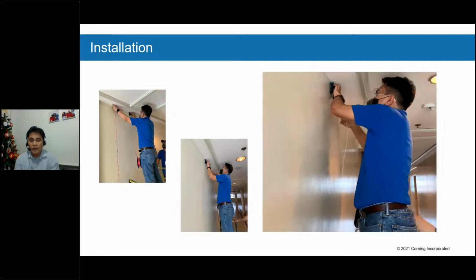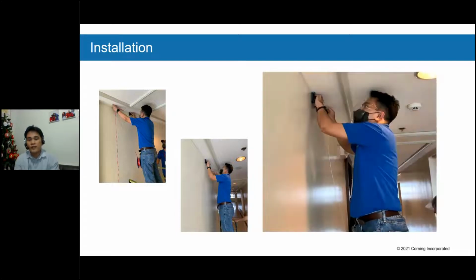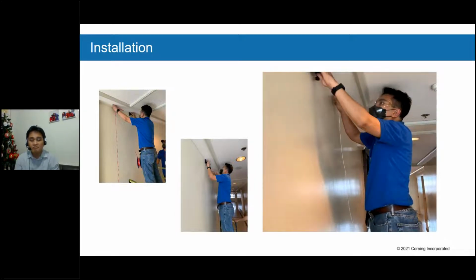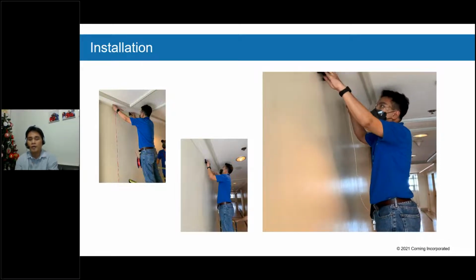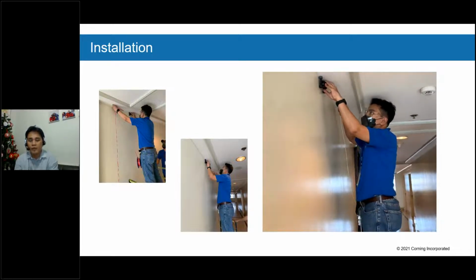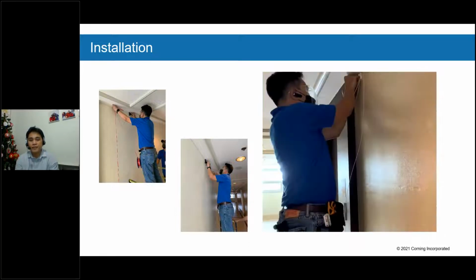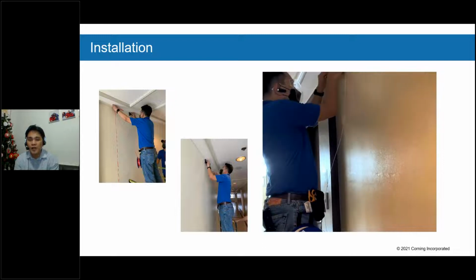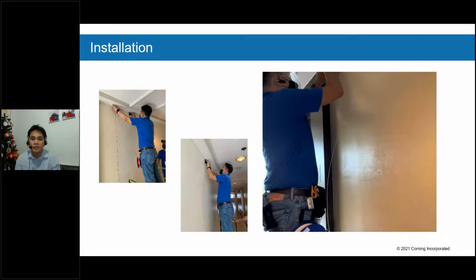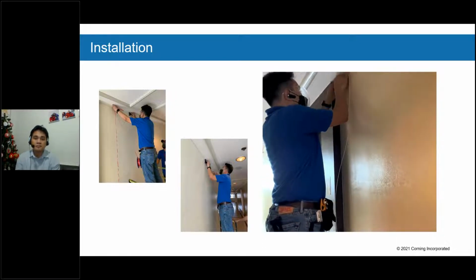Now the process is installing the 12 fiber micromodule into the ClearTalk hallway fiber pathway. Then, as mentioned, every unit will have its own small point of entry box, or what we call a demarcation box.